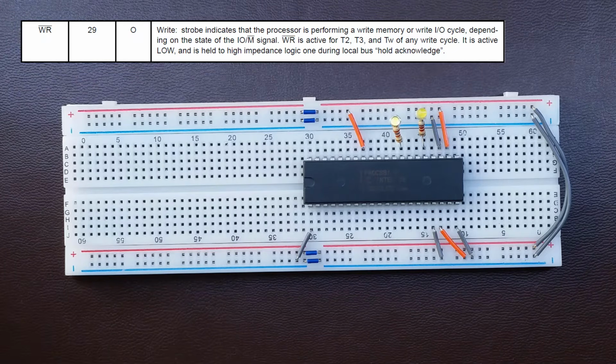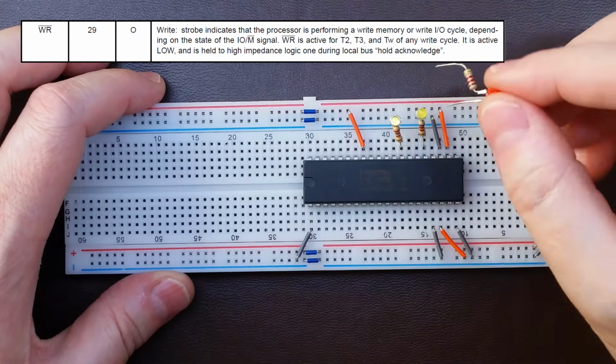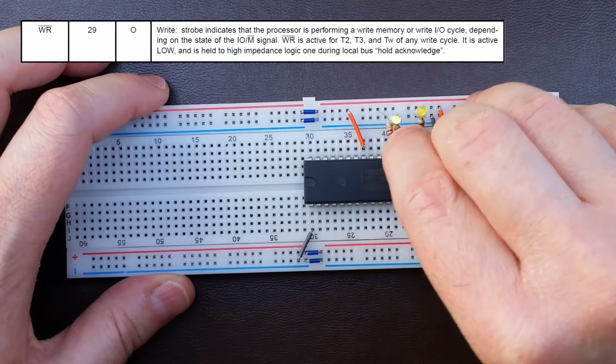Pin 29, WR, is an output. It goes low every time the CPU wants to write data to memory or the I/O. Let's hook an LED to it. Because we want the LED to be on when the signal is active, we need to pull it up to the VCC.